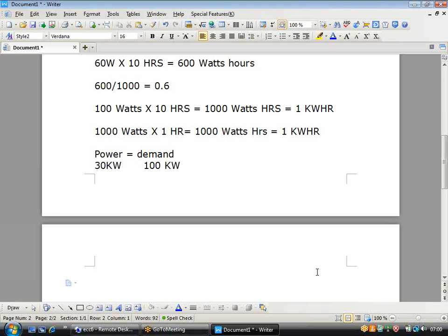That will be recorded in the power meter. There may be several readings available, but the system will show, among the readings, the one maximum instantaneous power that was demanded by the equipments in the factory, sustained for a period of 15 minutes. After you take the reading, you reset it to 0.